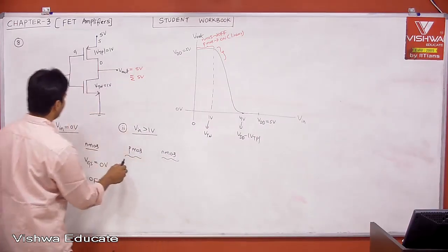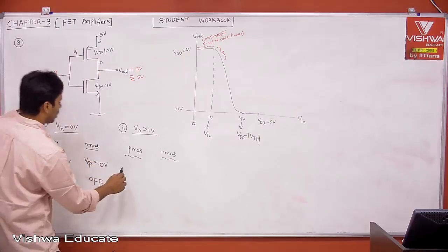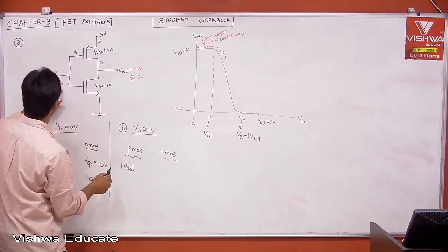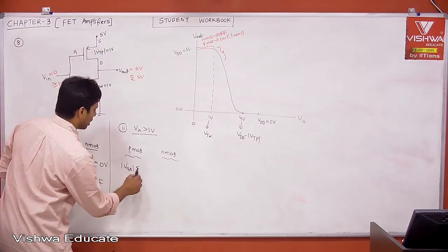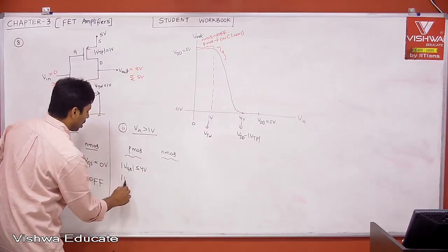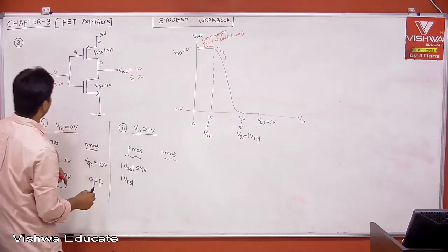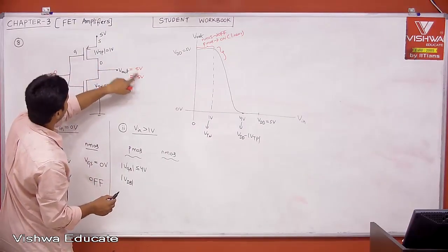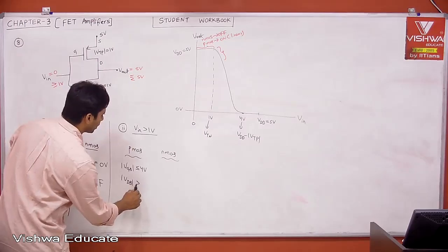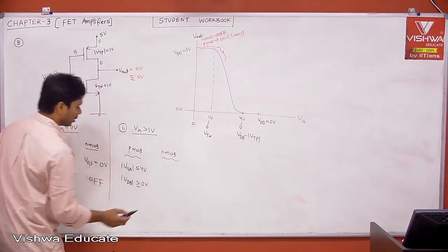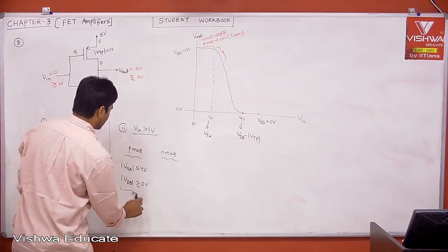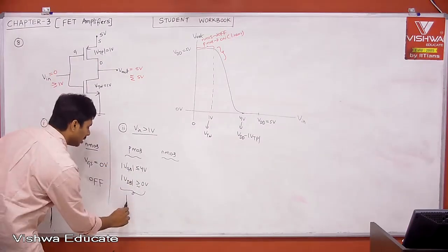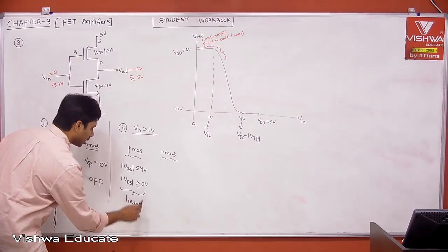Right? What is PMOS? When Vin is greater than or equal to 1 volt, what is your mod VGS? Your mod VGS will be 5 minus 1, which is less than or equal to 4 volt. Then what is your mod VDS? Drain is approximately 5, so it will be greater than 0 but close to 0. Now what is the region of the transistor? Your VDS is close to 0 and VGS is close to 4, still linear region only. If you calculate you will get it.